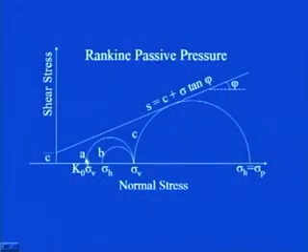If I take this Mohr circle corresponding to A, follow the pointer please, sigma V is the vertical stress at any particular depth, and correspondingly K naught into sigma V will be the lateral earth pressure at rest. We denote that coefficient of lateral earth pressure by K naught.